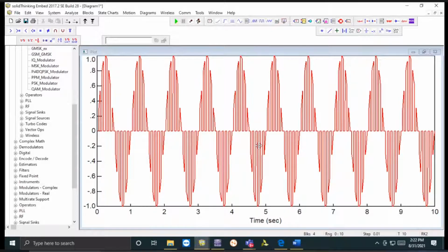So this is your sampled signal. Now, if you want to reconstruct the signal back from this one, you require a capacitor. The capacitor will be charged up to this point, and then when the signal drops down, it will start to discharge. It will go down, and again when it reaches here, it will charge again. So likewise, it will connect the peak points.